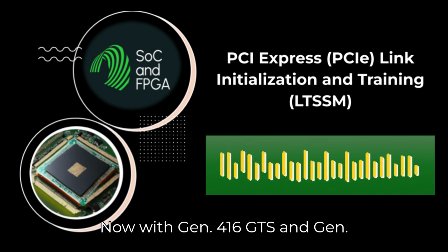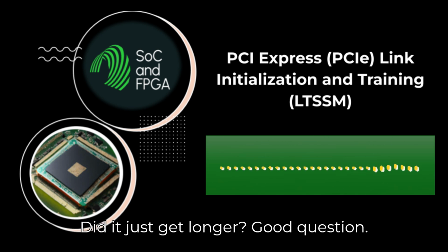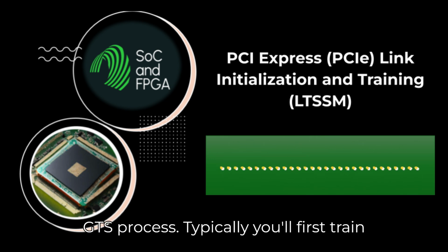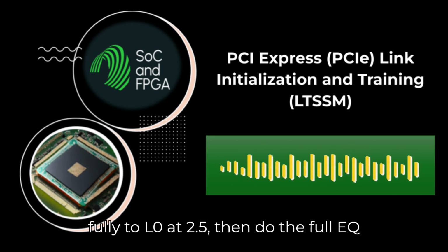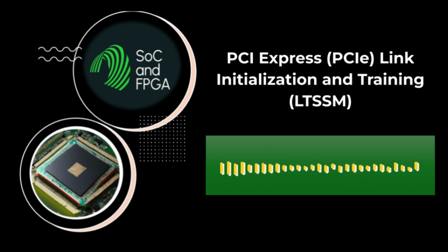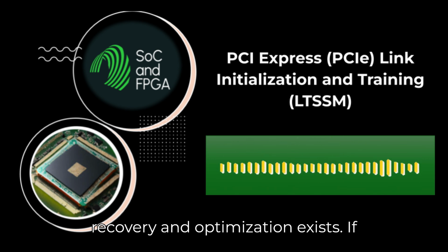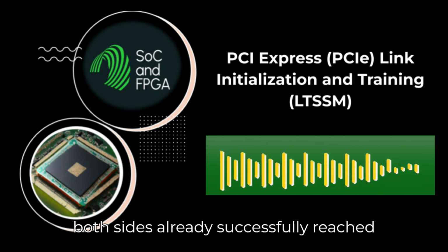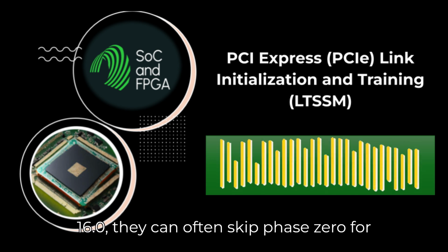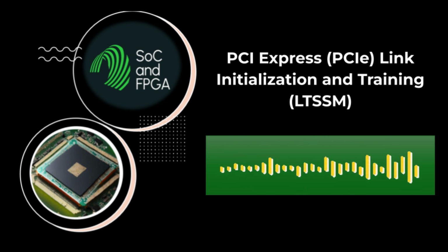Now, with Gen 4 16 GT/s and Gen 5 32 GT/s, did this process change much? Did it just get longer? Good question. For Gen 4 16 GT/s, it builds on the 8 GT/s process. Typically, you'll first train fully to L0 at 2.5, then do the full EQ phases 0-3 to get to L0 at 8.0 GT/s. Then to get to 16.0, one side re-enters recovery, and optimization exists. If both sides already successfully reached 8.0 GT/s L0 and both support 16.0, they can often skip phase 0 for the 16.0 GT/s equalization and go straight into phase 1 at 16.0 GT/s. Saves a bit of time.